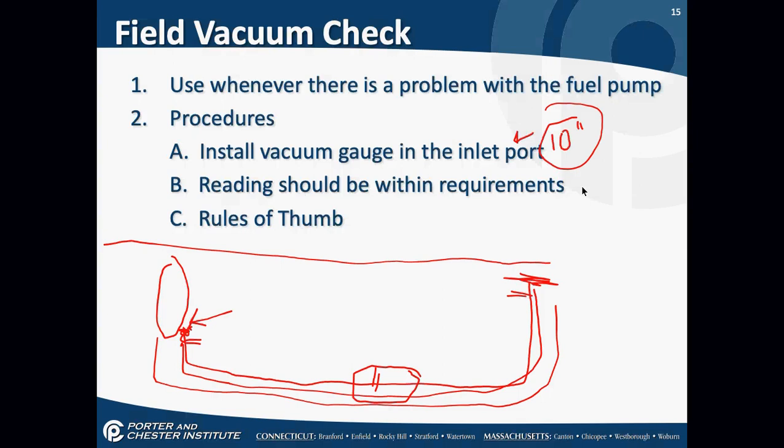They're supposed to be flagging that, because either the burner's not running right or there's a leak. Any increase of usage that's not temperature related, the oil companies on autofill need to be flagging. They were happy she was using more oil. They were making more money. But the reality is that should have been flagged.